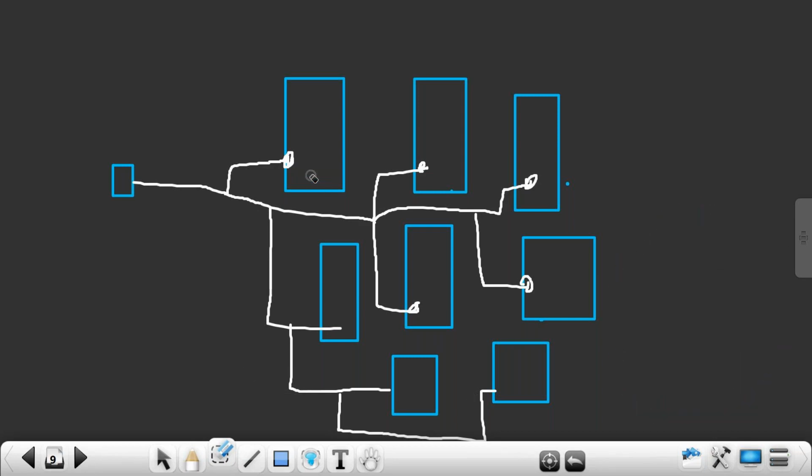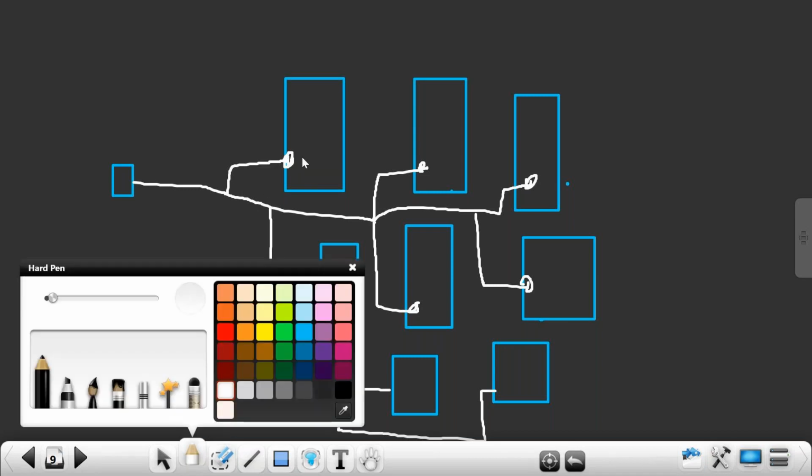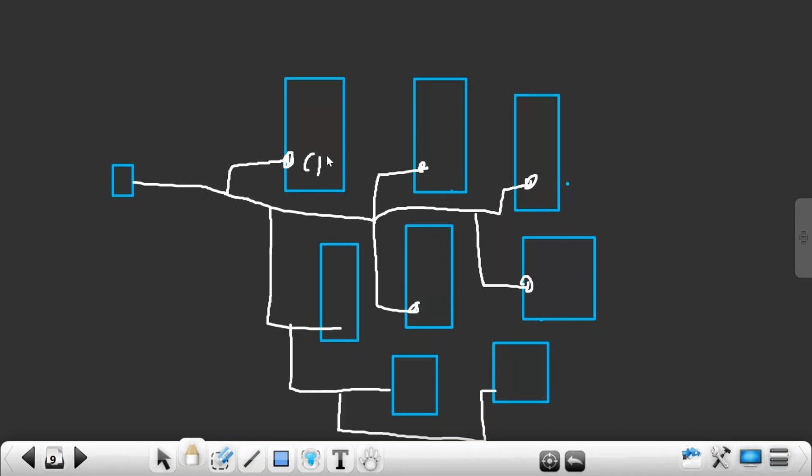So you have pin capacitance. Pin capacitance means every pin of a standard cell has some small capacitance. All this capacitance becomes the load capacitance on the port, the sum of all the capacitances. We are not connecting this capacitance; it is formed by virtue of their properties. Every flip-flop has pin capacitance, and you also have net capacitance. All this pin capacitance and net capacitance will become the load capacitance.